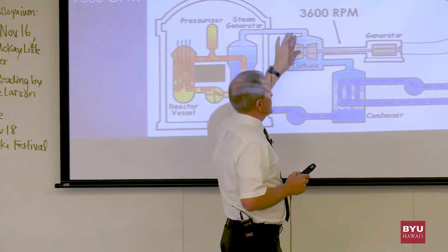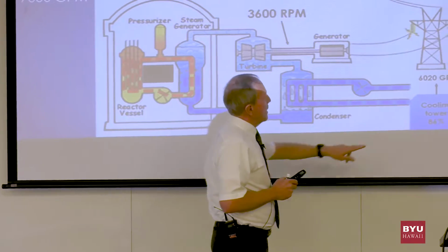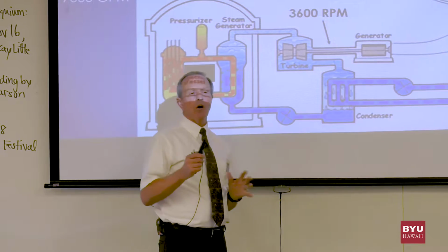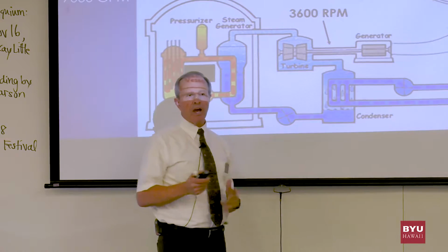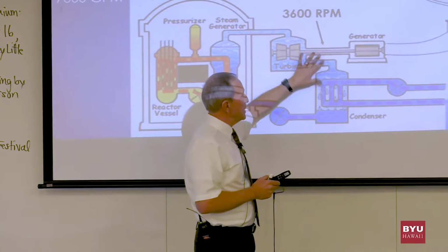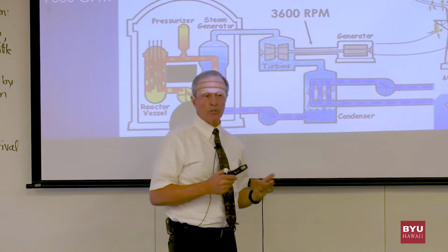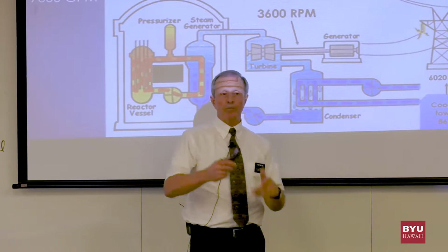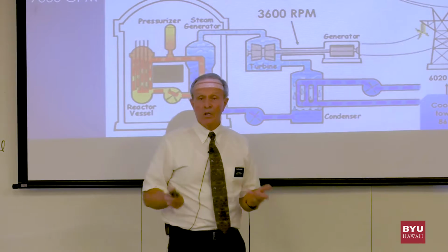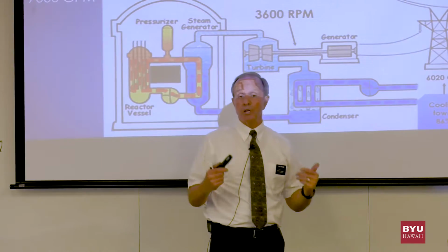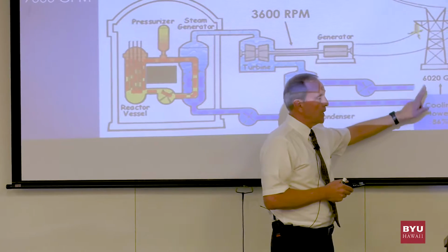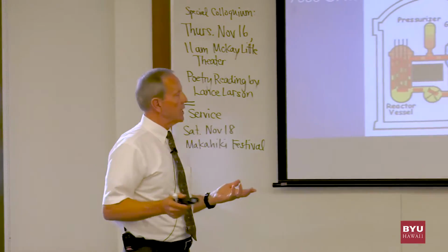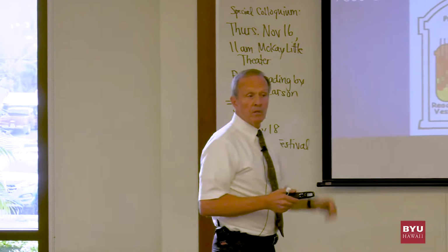What happens too, you have to realize, is we're using 7,000 gallons a minute here. You have cooling towers. Why would you have cooling towers? Once this steam hits this turbine, you've got to take all the heat out of it and put it back into a liquid. You can't pump steam. So you're going to take all this steam and bring it back down to a form that you can pump, which is water. You have to extract the heat, but you want to do it economically. Every time you extract some heat, you want to put it back into your system because it took heat for your system to function. So you have to put this heat back in your system as much as you can, but the cooling towers are taking the heat off, and you're going to lose about 6,000 gallons a minute, about 84 to 86% of your water goes out the cooling towers. You'll never see it again.